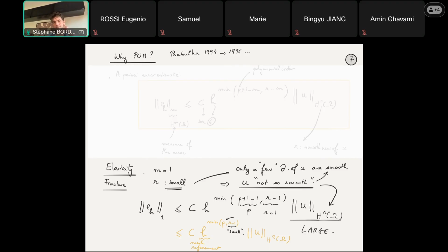So when you compute the integral of, let's say, grad u squared, that's going to be a large number. You don't want large numbers here, because that will be a coefficient in front of the h, which will really be a pain. Because the larger this value, the higher the curve will be in terms of error. So the higher the convergence line will start, let's say.